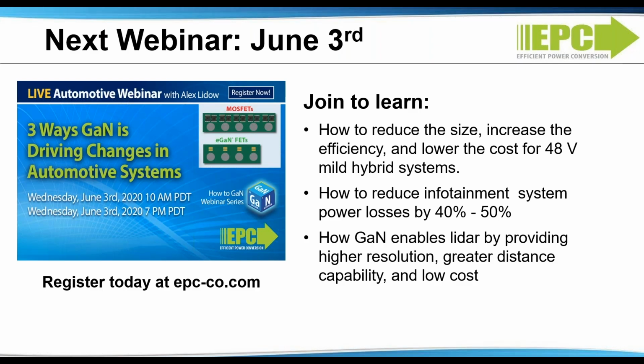And we really do separate it out by the fundamental intrinsic failure mechanisms. And over the last 10 years, we've made each generation more and more robust by focusing on reducing the sensitivity to those failure mechanisms. It's also how we got rid of dynamic RDS(on).